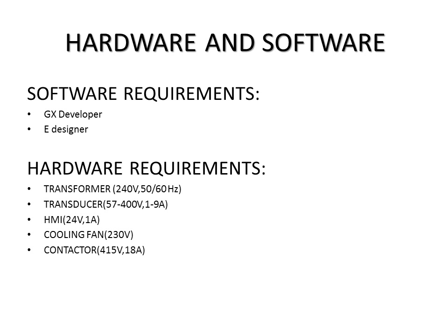Hardware and software. Software requirements are GX Developer and eDesigner. Hardware requirements are a transformer 240 volts 50 to 60 hertz, a transducer 57 to 400 volts 1 to 9 amps, a human machine interface 240 volts 1 amp, a cooling fan 230 volts, and a contactor 415 volts 18 amps.